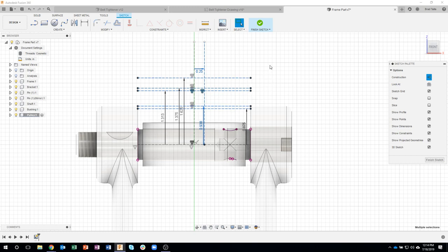Now I'm going to share that tip in my upcoming tips and tricks, but basically if you draw a window from left to right, it's only going to select what's fully inside that window. So you'll notice it didn't select any of those lines because they're not fully inside. Now if I came down like this, it'll select some of the stuff. But if I drag from right to left, it's a crossing, and anything crossing that window gets selected. So kind of a cool tip. So you're getting some preview tips here.